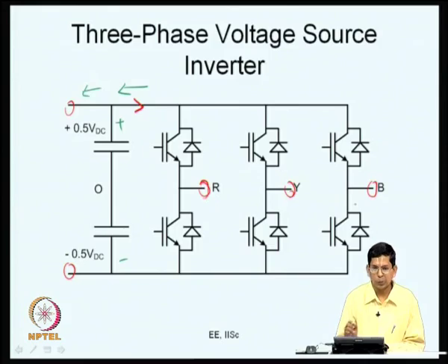If you look at it correspondingly on the line side, what happens is the phase difference between the voltage and the current waveforms. When the voltage and the current waveforms differ in phase only within plus 90 to minus 90 degrees, power flow is in a particular direction. If it is beyond 90 degrees, or close to 180 degrees, the power flow is really in the opposite direction. So, as we saw earlier, this is actually a bidirectional converter.